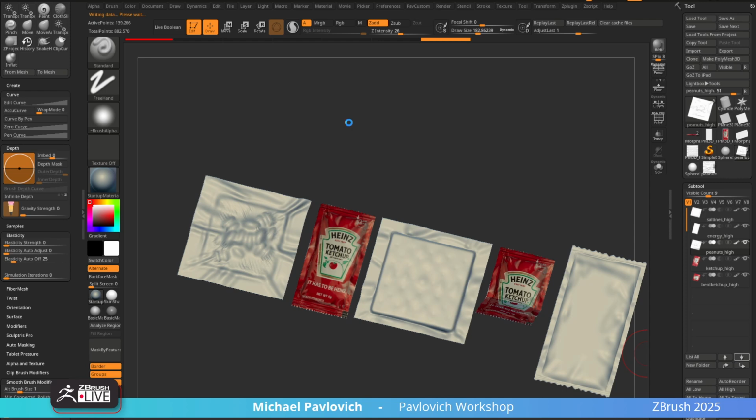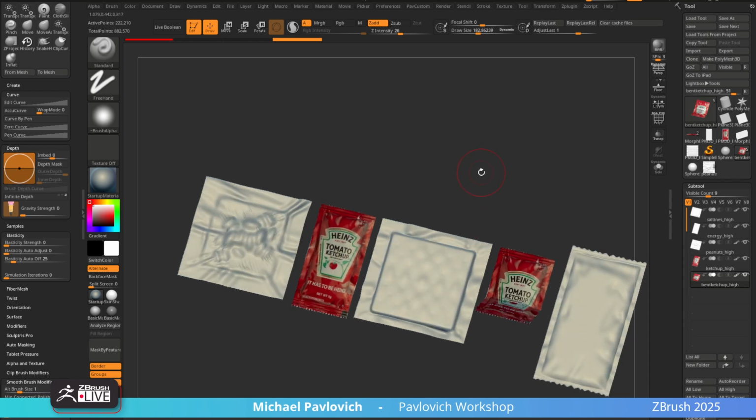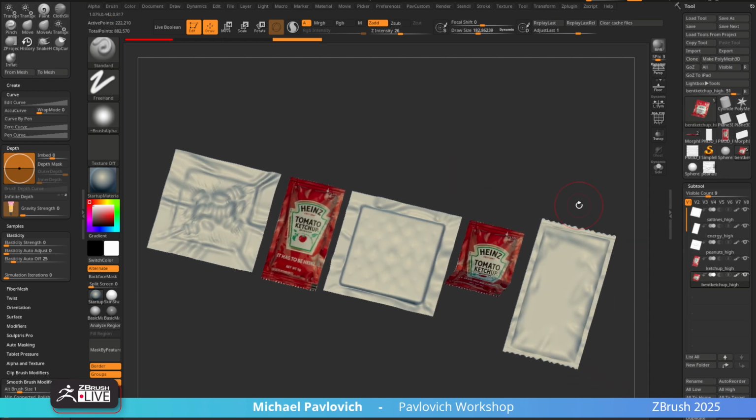And then we're going to make our game res. That's going to need a low res. Substance Painter will auto UV for you, but we'll use ZBrush to UV our stuff. The other thing you might need to worry about is if you wanted this all on one texture set, assigning one material to these, I'm not sure you can do in ZBrush. I would export the low reses into Max, Maya, Modo, Blender, Cinema 4D, or whatever, assign a material to those, and then export that low. I'm going to make these all different texture sets because it's not a huge deal and we can work around it. But just want to shout that out.